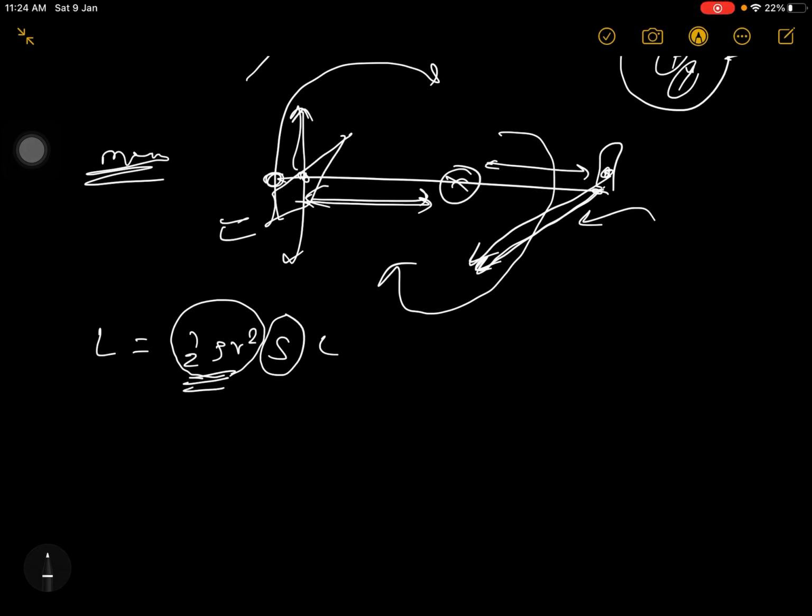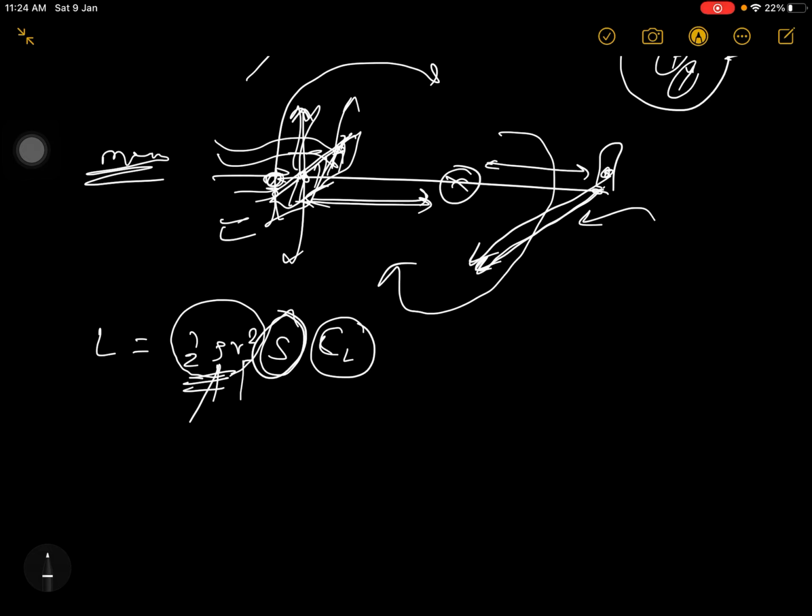Whatever wing we have here, how much dynamic pressure is experienced by the wing. So rho means what kind of fluid is reaching the wing, the density of the fluid. Then what is the velocity experienced by the wing? That velocity you keep here. What is the planform area of the wing? And in the last you substitute the coefficient of the particular force being produced on the wing. But we are producing lift, so we say CL, coefficient of lift.